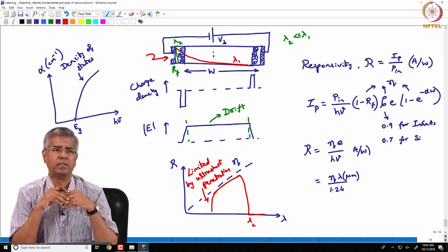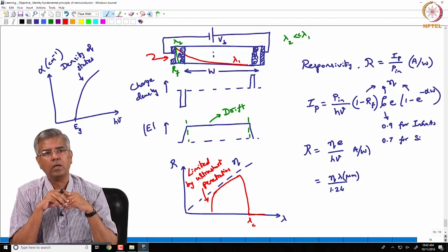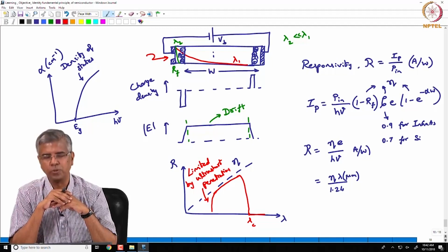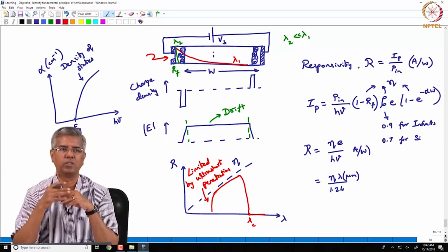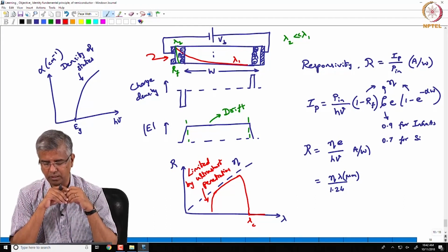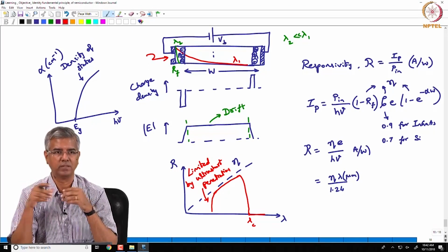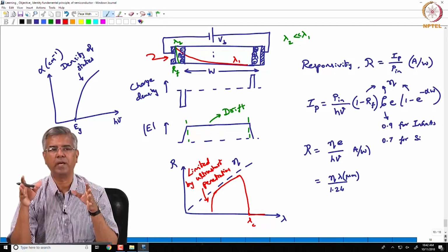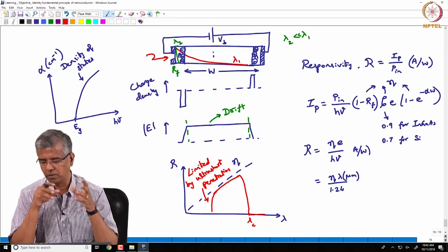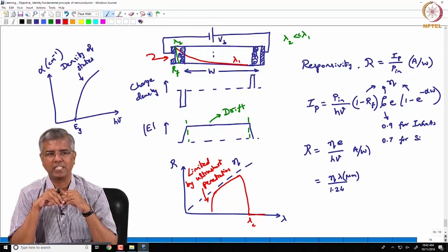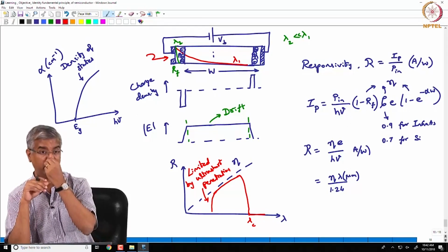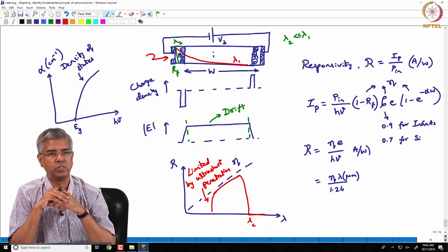Part of it could be. Yeah, we're just looking at the first level thing, but if you leave light over there, some of those photons can come back. But you typically design your photodiode for that longest wavelength of operation. So at the longest wavelength, it should be absorbed completely. So then you basically try to maximize that term. So you try to maximize that to 1. So e power minus alpha w, that fraction is going to be very close to 0.